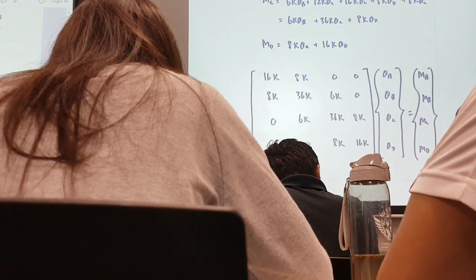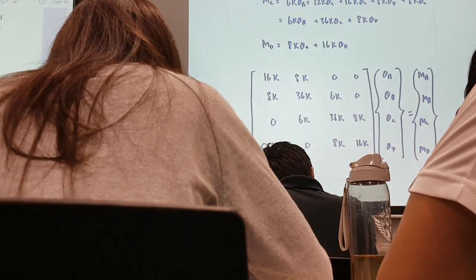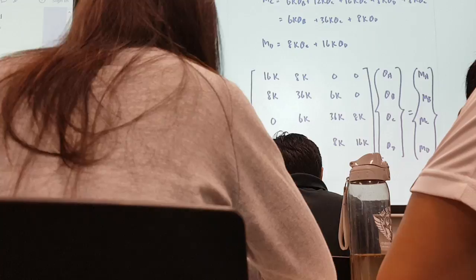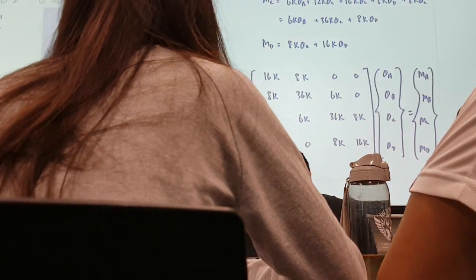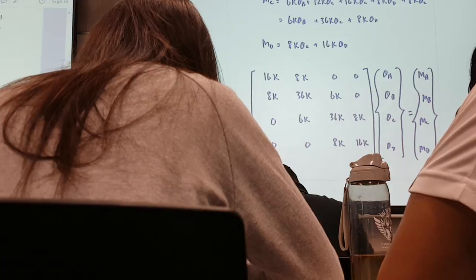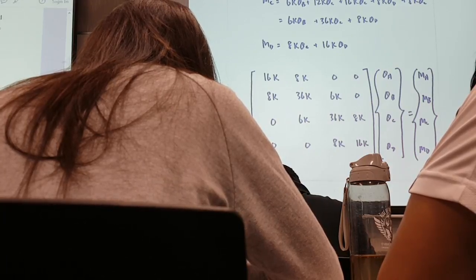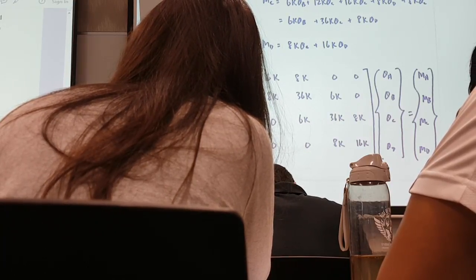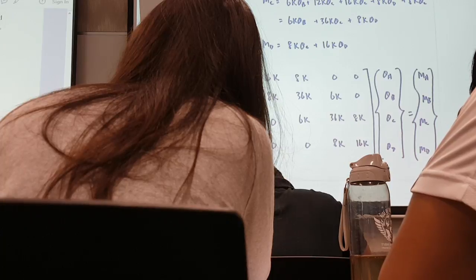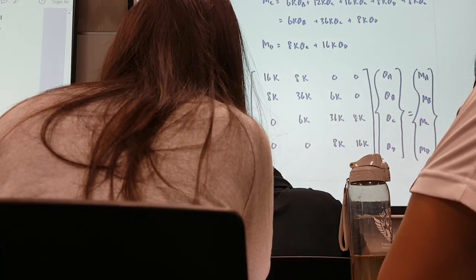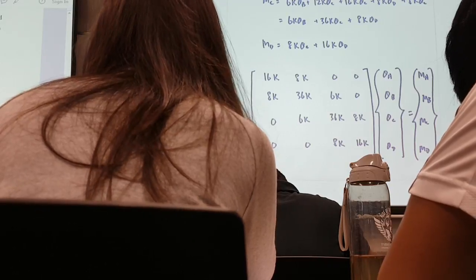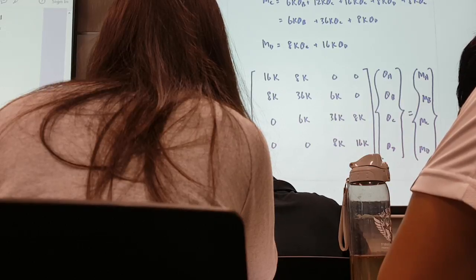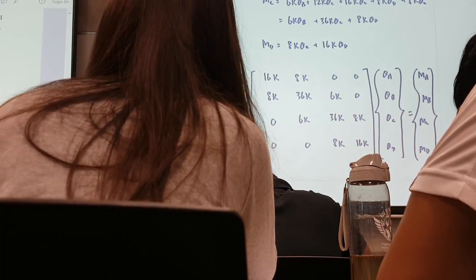With that in mind, you know that you need to apply the fixed end moments, correct? And also you know that you have to use the formula P equals PA minus PF. So this is a more intensive question. And of course the question says that all the flexural rigidity is EI. It's just that the length is different. But you really have to account for the length when you calculate all the M1, M2, and PY1 and PY2. Alright, so let's move on to the solution.